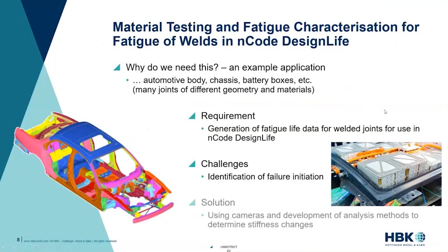Fatigue simulation and prediction of welded joints is more complex and requires joint fatigue properties, not just material properties, that combine both the joint geometry and the joint material.